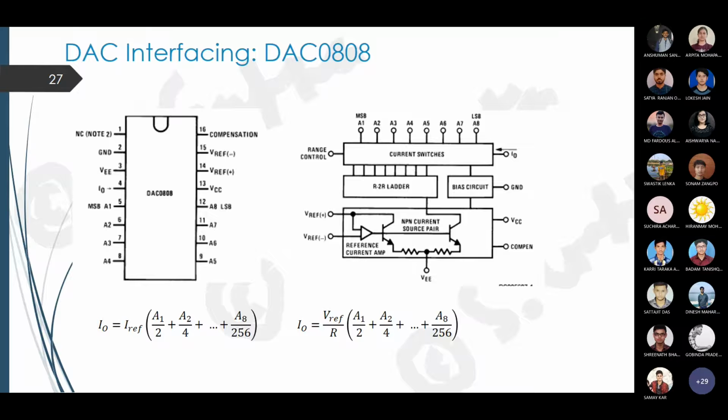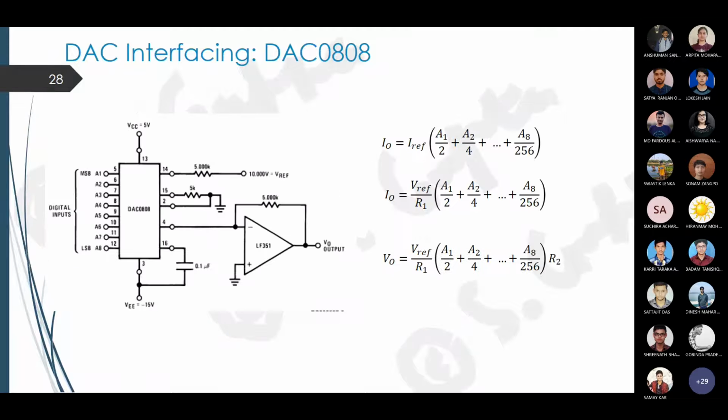And then we have also used the DAC, DAC 0808 only. So we are just replacing the 8085 and working with the 8051. The advantage we get here is that we do not need an additional peripheral interface controller like the 8255, and so that will definitely reduce our cost.